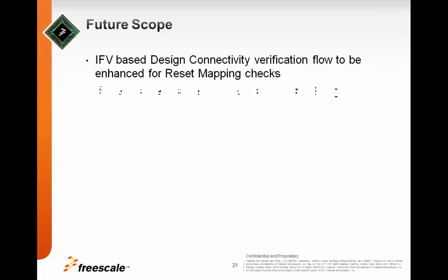Future scope: we are working on enhancing the formal based design connectivity verification flow for reset mapping checks, as well as the IFB based verification of the low power control logic.